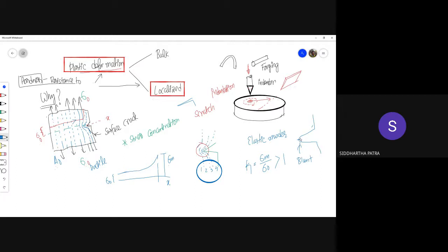So obviously the plastic deformation is also higher over here, and because of that, there can be a blunting of the crack tip. I'm not saying the ductile material can always prevent crack propagation, but blunting essentially reduces the stress concentration factor K, because it is dependent on the sharpness of the crack.